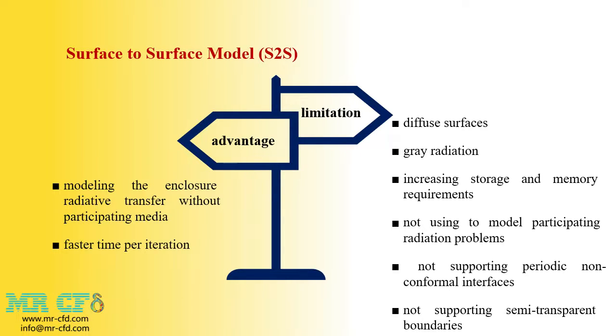First of all, this method is one of those radiation methods that consider surfaces as diffuse. Second, it only implements the gray radiation mode. Third, the storage and memory required to solve this radiation model increases rapidly with the increase in the number of surfaces. Of course, it is possible to minimize the surfaces of the model by using the ability to create a cluster, and hence it increases the speed of the solution. Regarding the concept of clustering, comprehensive training will be given later.